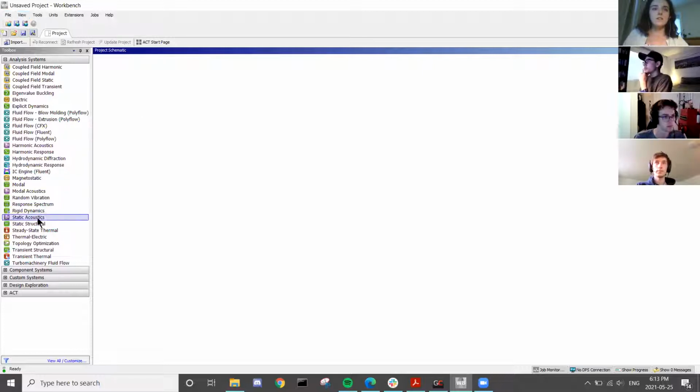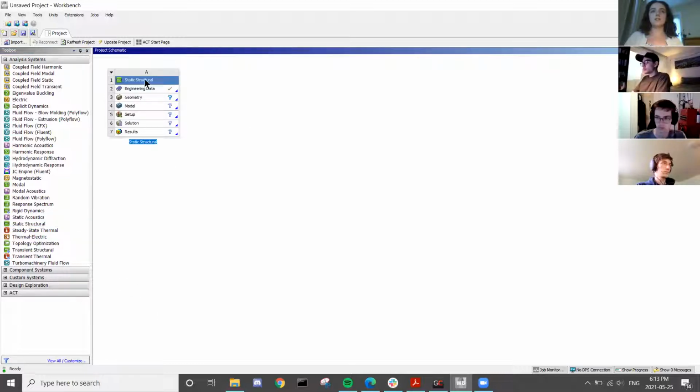Okay. So then this is what you see on Workbench. This is kind of your main page. And then open up a static structural. So now you get this guy. So double click on engineering data.